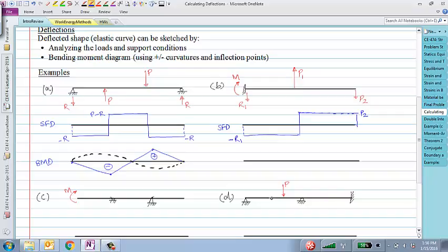What would the bending moment diagram look like? What value would it start at? 0? M, positive or negative? Positive. So it will indeed be positive. Let's say some value M starts here. The derivative of this is negative, so it would quickly go out to some value here, and then it would increase up to 0 out here. Make sense?